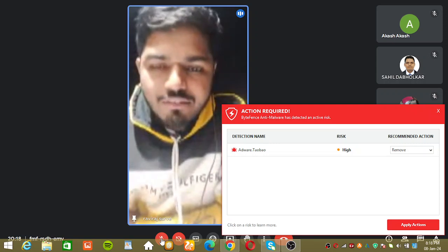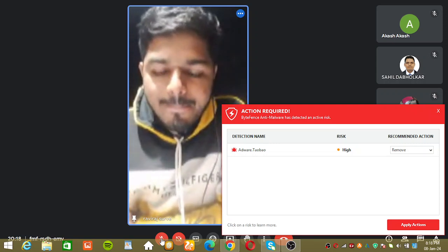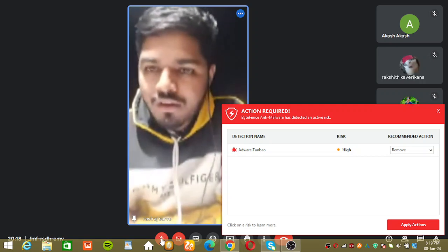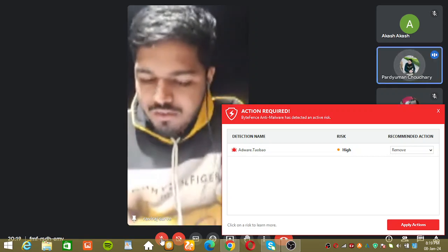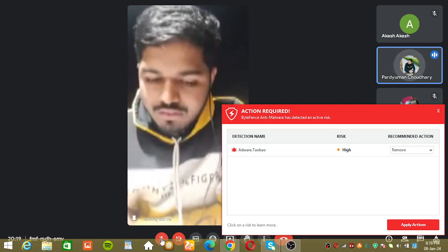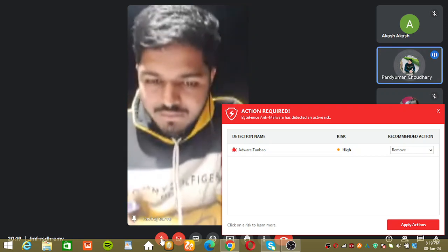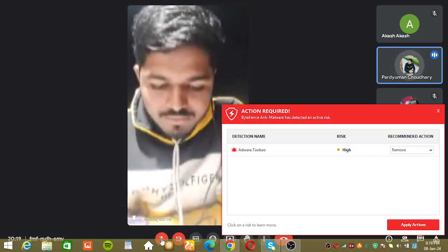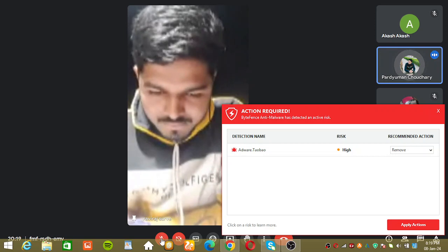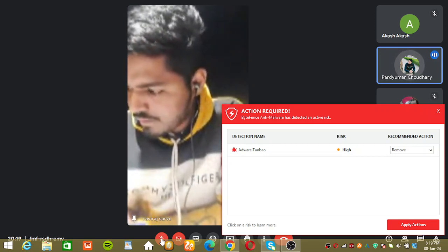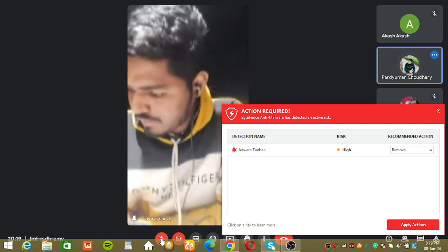So the next safety is the safety valve or relief valve. What is the function of the relief valve? Yes, Pradyuman. The function of the safety or relief valve is that when the compressor produces a lot of pressure inside it, and due to any reason that pressure is not getting out of the compressor, then this safety comes into action and releases the excessive pressure from the compressor.